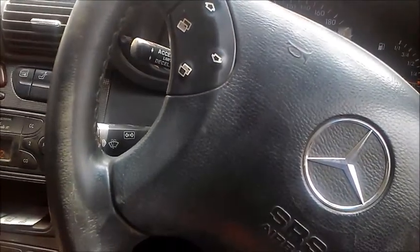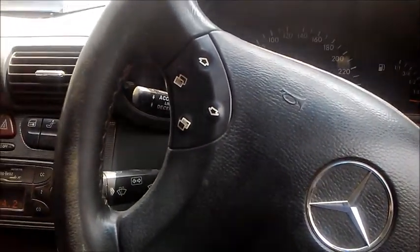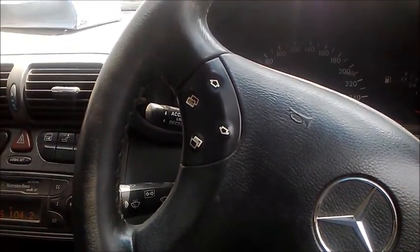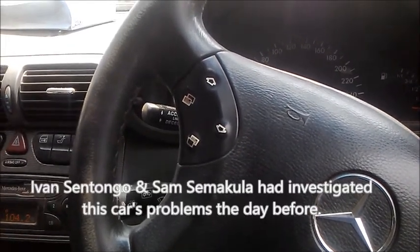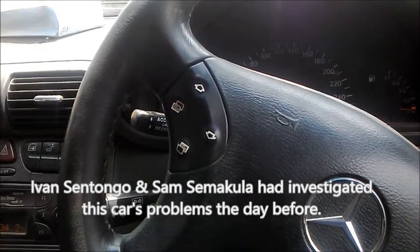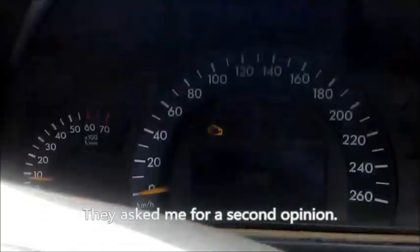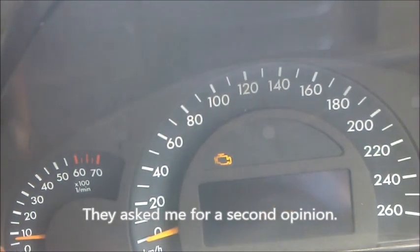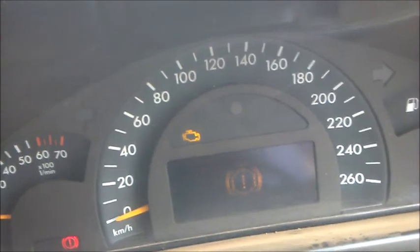I think I need to test drive it to verify the complaint, but I'll begin with looking for fault codes. Usually Mercedes, when they have transmission issues, will very easily set trouble codes. So I'm going to look there first, and if you look, the engine is running right now. You can see from the tachometer the engine is running. You can rev it up and you see that.